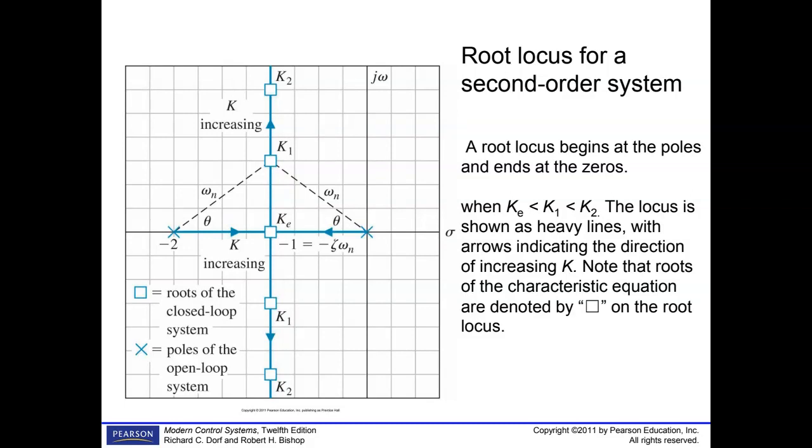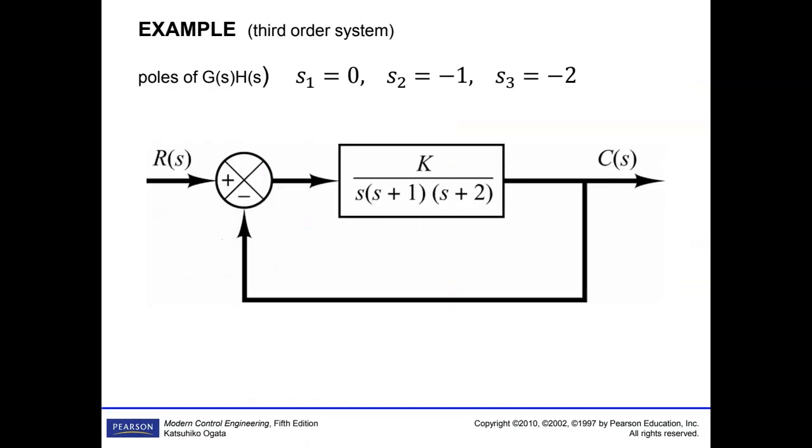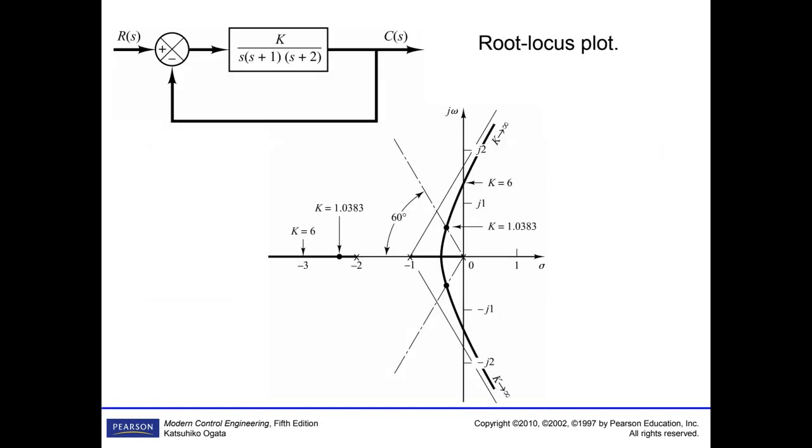One pole is located here, the other pole is located here. These two are a couple, and then this is one which hasn't got any further effect on this one, far away from the origin. There are several. MATLAB is going to draw those anyway, and these are the cases where the poles are located, the trajectory of the root locus curves.